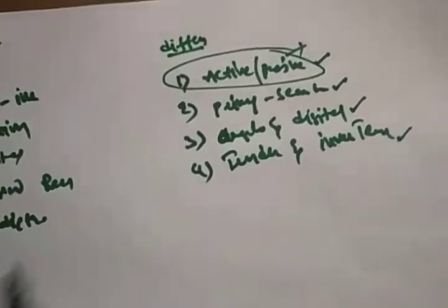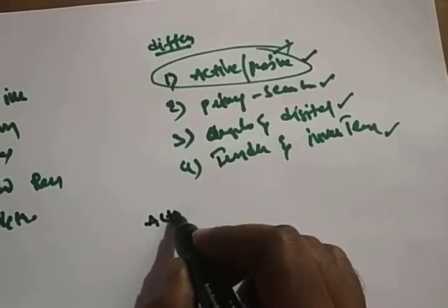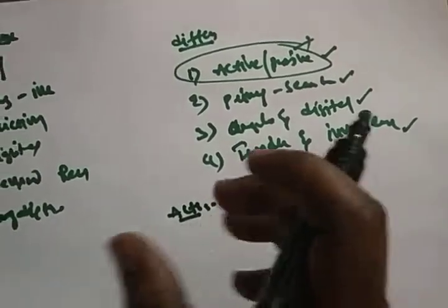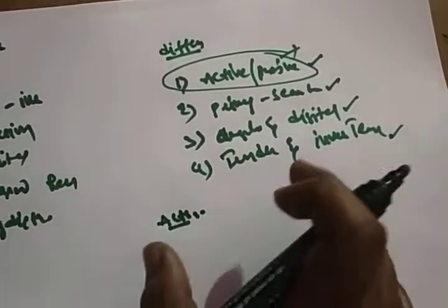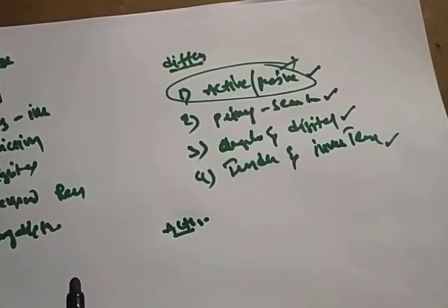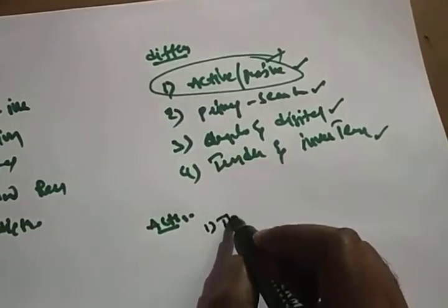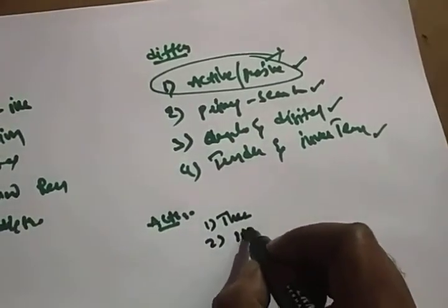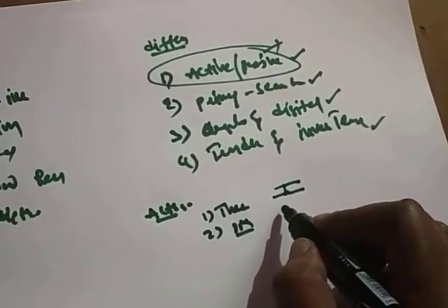So what is an active and passive transducer? What is an active transducer? These are the transducers that don't require external electrical supply, right? So whatever voltage comes out from the transducer is enough to operate this active transducer. What are the examples? Thermocouple and piezoelectric transducer. Thermocouple: two dissimilar metals joined together, right?